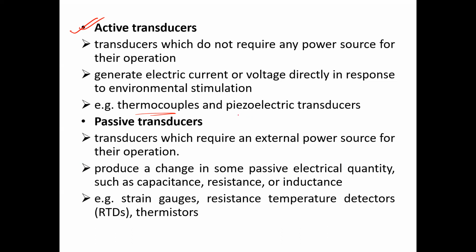And piezoelectric transducers. These transducers are designed with piezoelectric materials. Piezoelectric materials are materials which generate electricity when there is some deformation in their shape. If some mechanical stress or force is applied to piezoelectric materials, their shape is deformed, so the crystal structure is deformed, and that results in generation of some electricity. So those can also be classified as active transducers.